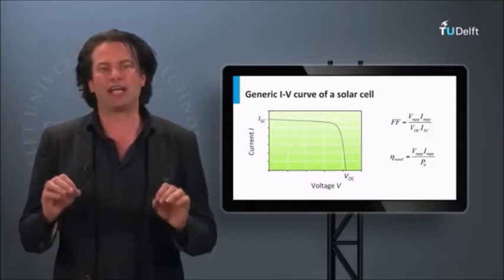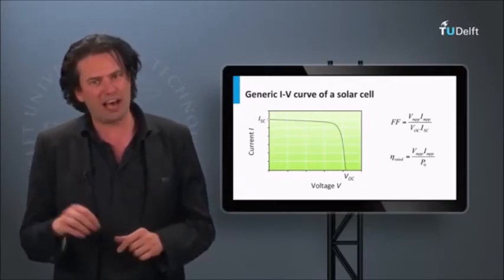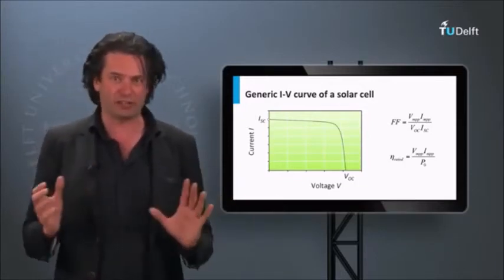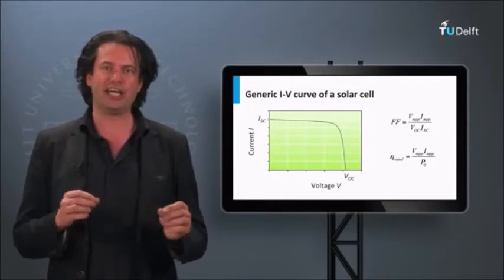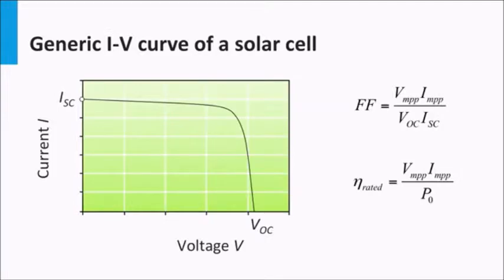First of all, I would like to introduce a new term, the IV curve. So far we have been discussing the JV curve at the solar cell level, J being the current density, current per unit area. But at the module level, the total current that the module can generate is of more interest. Hence, we look at an IV curve, or the current voltage curve. As the area is a constant, the IV and JV curve of the solar cell or solar module will have identical nature.